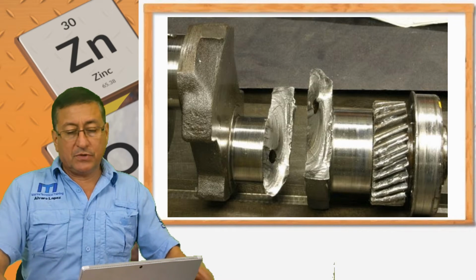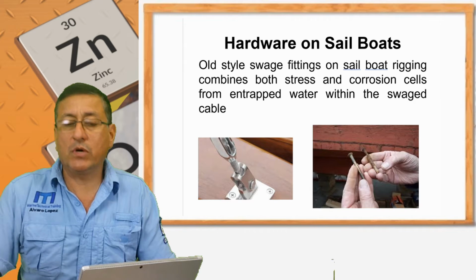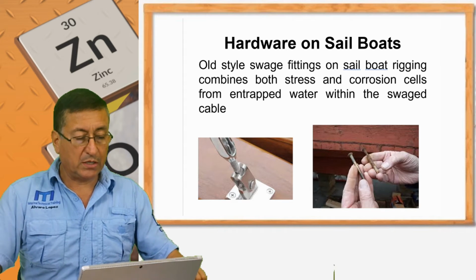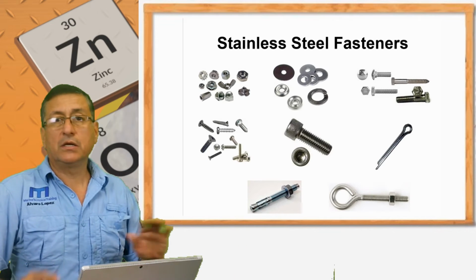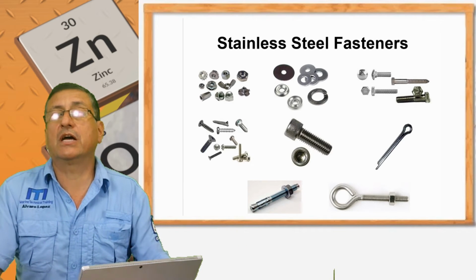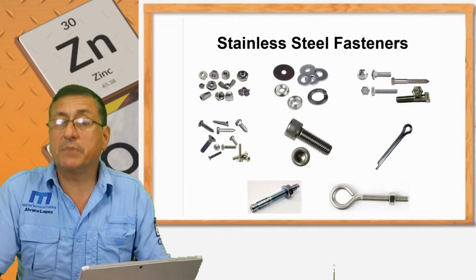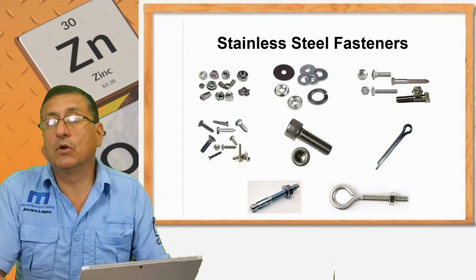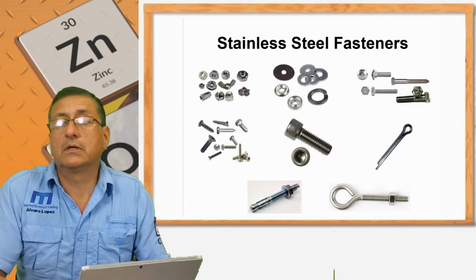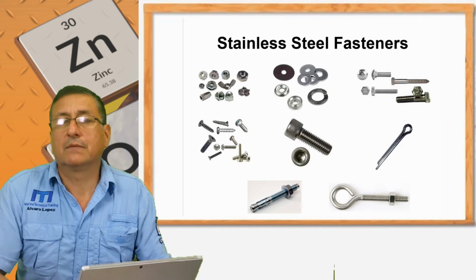Okay, my friends, for that reason, don't forget to use appropriate marine grade hardware. Only by using marine grade approved hardware do you avoid millions of problems and protect your boat. At the end of the day, it's too expensive to repair boats because you used regular bolts, regular steel, residential bolts. Be careful with that.